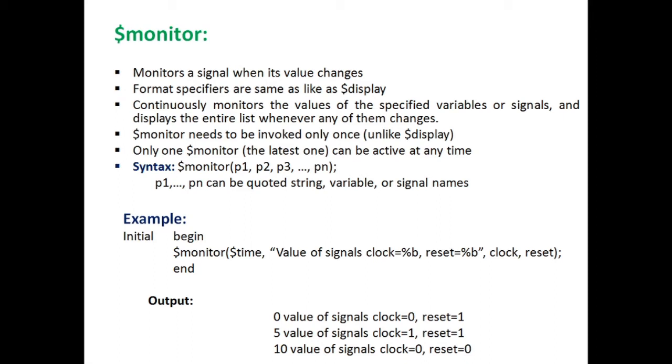Of course the syntax is the same as $display, that is p1, p2, where p1, p2 can be signal names, variables or strings or whatever it is. So let us see the usage of $monitor by using the Xilinx tool now.